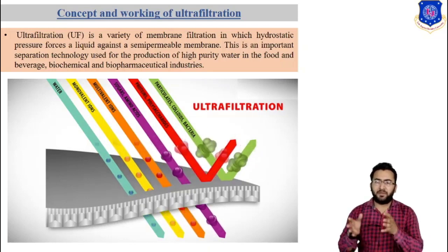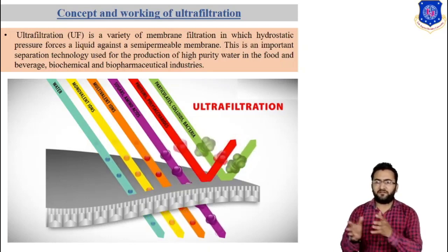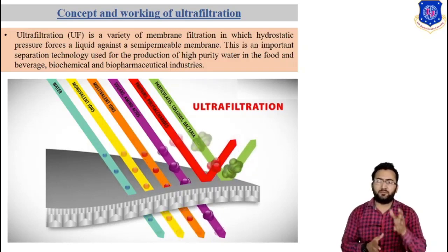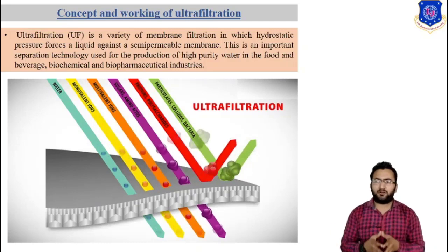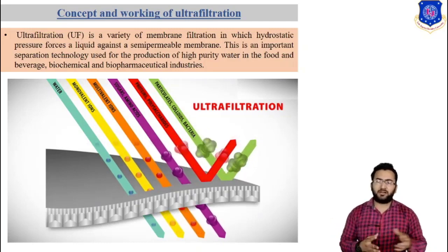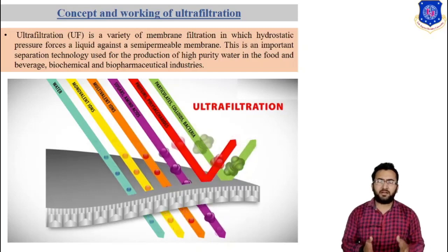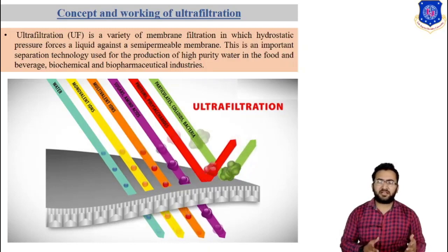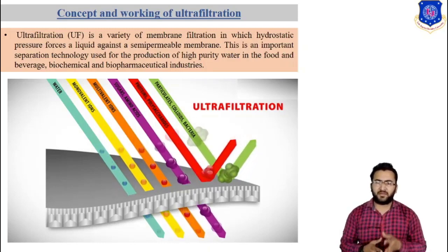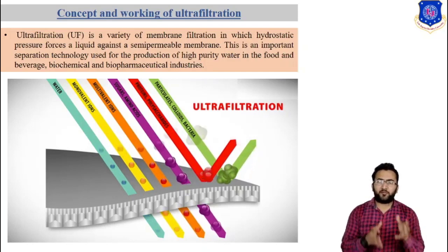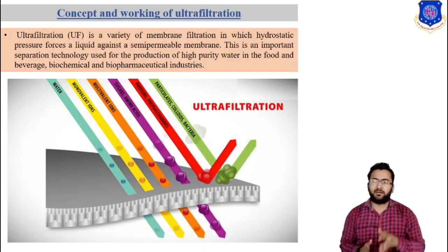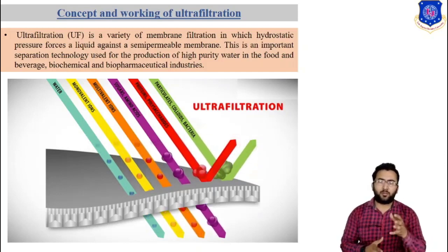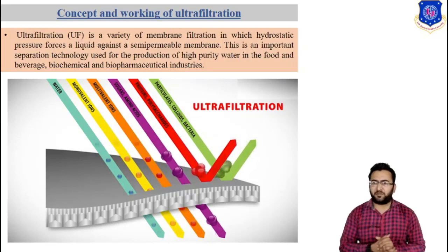Molecular weight cutoff is the minimum molecular weight at which rejection is 90%. To design the membrane, the molecular weight cutoff must be taken as about half of the lower molecular weight which is to be retained. Ultrafiltration membranes are given a nominal rating referring to the molecular weight of a test solute that is 90% rejected by the membrane under standard conditions. Since this does not imply absolute retention by the membrane, this designation is sometimes referred to as nominal molecular weight cutoff of the ultrafiltration membrane.